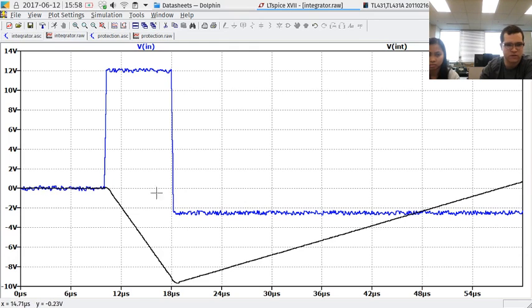So here's 0 volts, then we switch to the reference. The integrator is inverting, which is something worth noting: when there is a negative input voltage, the sign bit at the output is going to be high, which means that if there's a negative input voltage, this slope will actually go this way, and we'll use the positive reference, which will cause it to go back down.